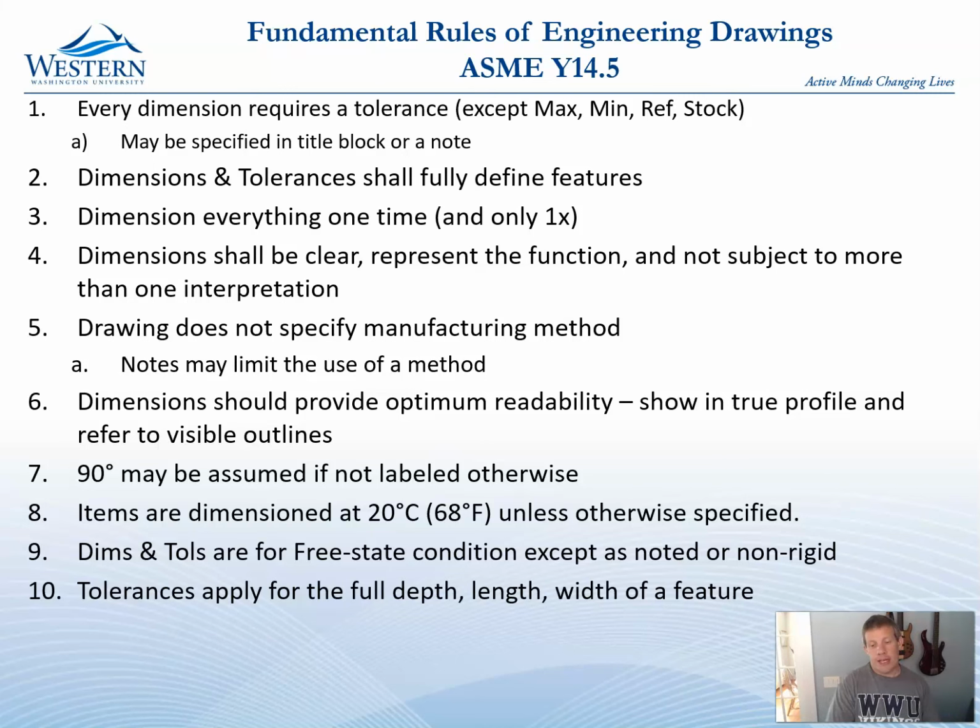Tolerances apply to the full depth, length, and width of a feature. Now this one is a little bit ambiguous, but what it means is if we label a position of a hole up on the top surface, that position tolerance is supposed to apply all the way through. But that's a little bit hard to tell exactly what's going on. It's hard to tell where the center of that hole is,